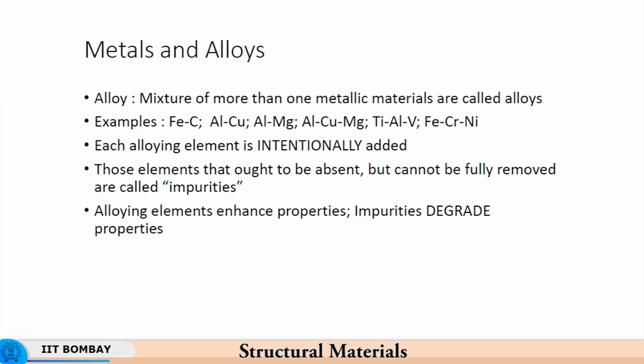So, if you make aluminum lithium alloys, lithium has got a much lower atomic weight as compared to even magnesium. So, naturally you are trying to reduce the weight of the alloy that is being used, plus increasing the strength. So, the strength to weight ratio increases, plus you are taking the advantage of a reduced density of the resulting alloy. So, now the benefit is twofold.